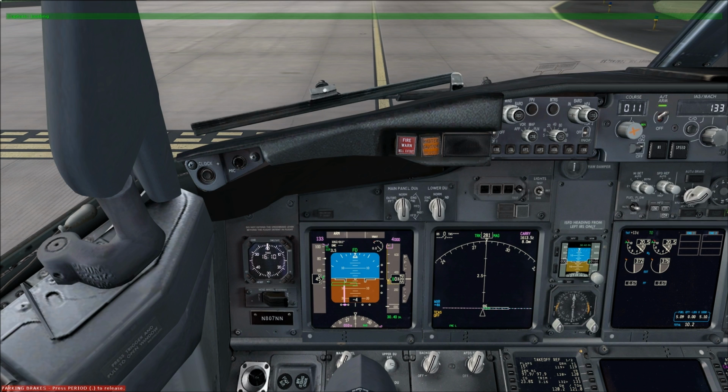And I even saw one thing where someone suggested, what about extending the flaps to gain more performance? Well, you would gain performance in that, but you also run the risk of selecting the wrong configuration. For some strange reason, in the high stress environment, you might end up retracting the flaps instead of extending them.